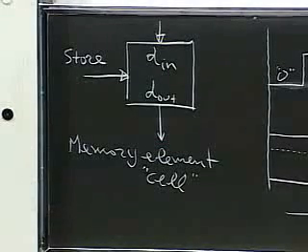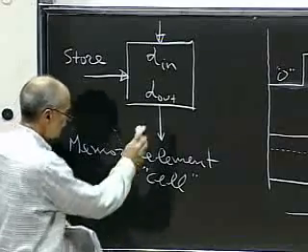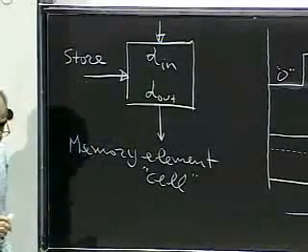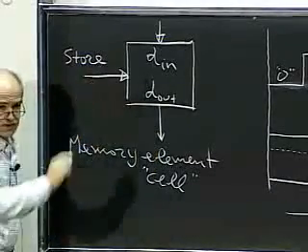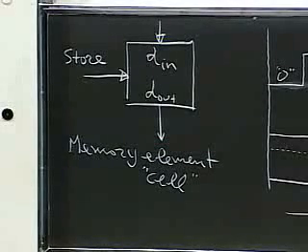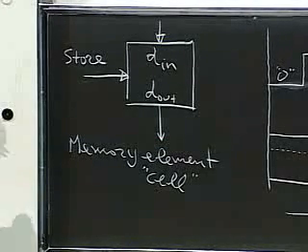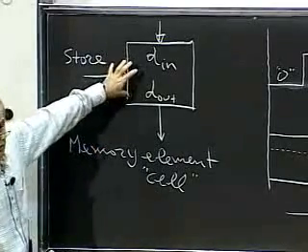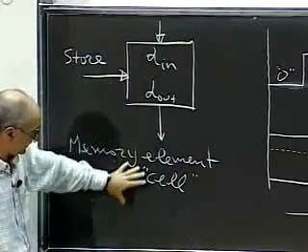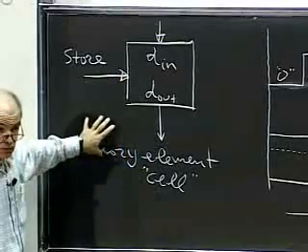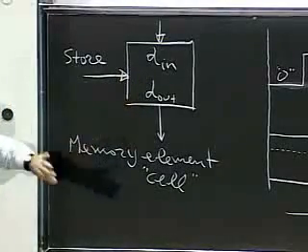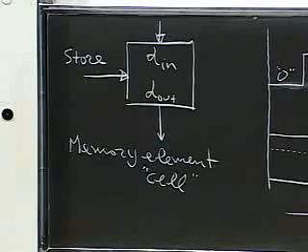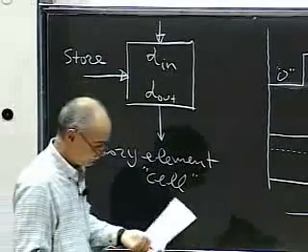It would remember the output state. And not only that, but in principle, it should be undisturbable, okay? In other words, I may do something to this D out, but it should not flip the state. And that comes about quite a bit because in actual integrated circuit memory, there's lots and lots of nearest neighbors to this cell, which, when they're flipped, have a cross-coupling to this cell. The cell must be designed robust enough that it doesn't flip, okay, that no coupling actually occurs.